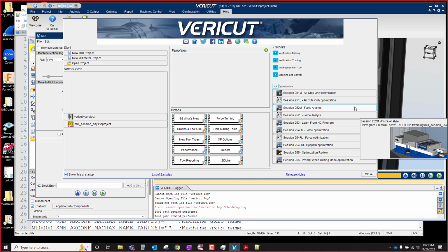God, I wish CNC software would fix that. There's a whole bunch of stuff. One of the things you'll notice, especially if you're doing a dynamic mill with, say, a half-inch end mill on a 4-inch internal circular bore, is that you're going to be overfeeding at the center. If you program it at 200, the very first little spiral gives you a much higher chip load than once you start opening up that hole, and then the chip load starts to go backwards.